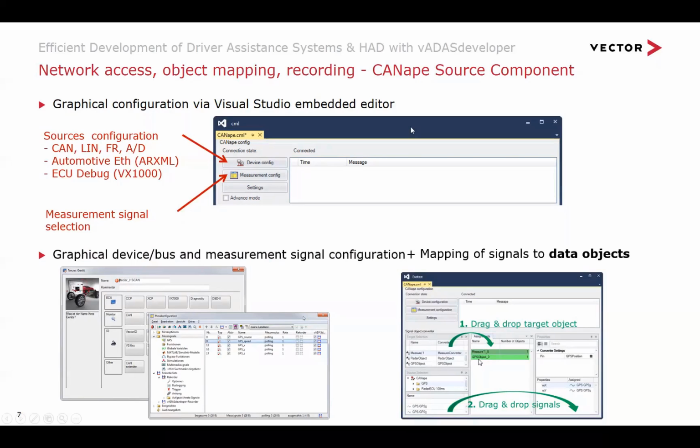And this is an application class, but on your bus, on your network system, you have serialized information. So somebody sends you a GPS X signal or a GPS Y or a GPS course or whatever. But you don't want to treat it signal by signal in the algorithm, but rather you want to assemble all the different properties that you get by the signal into one single container, and that would be the GPS object.